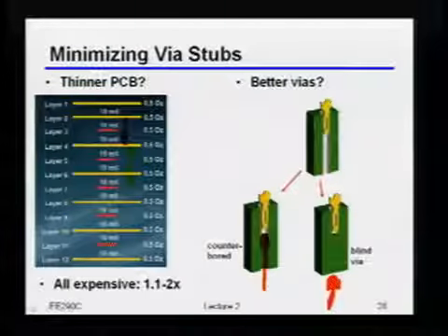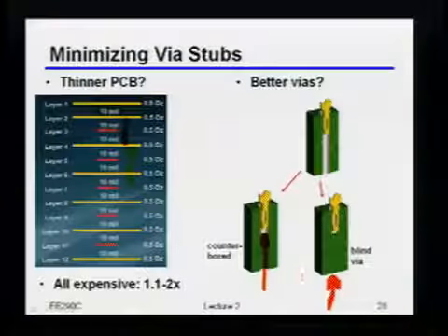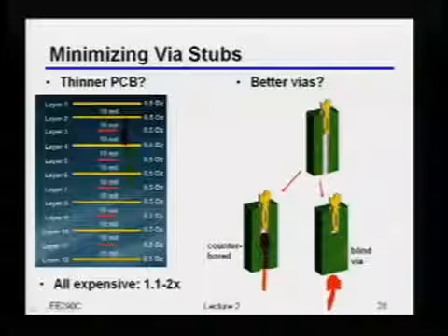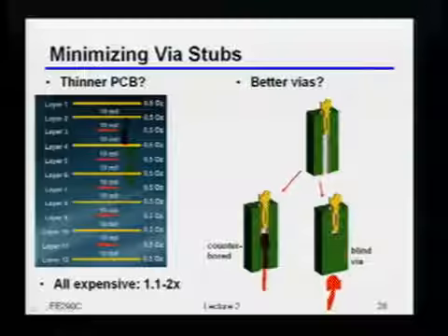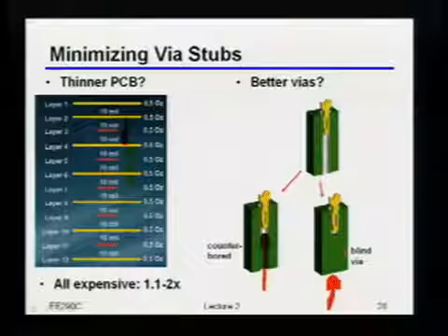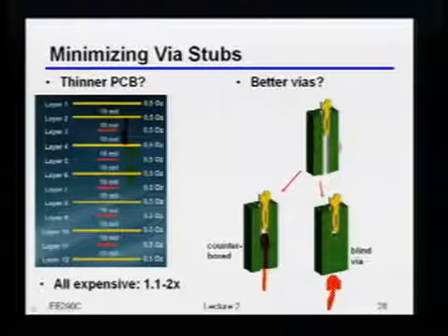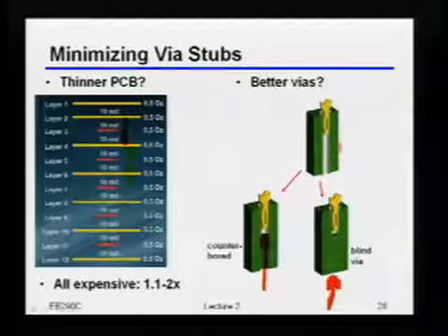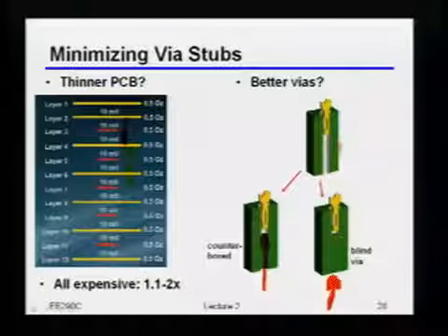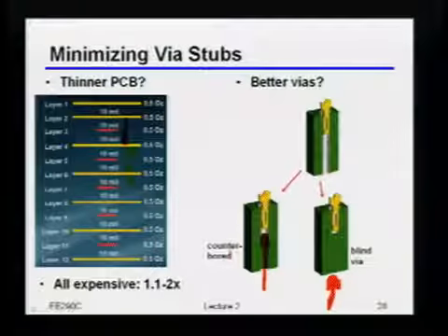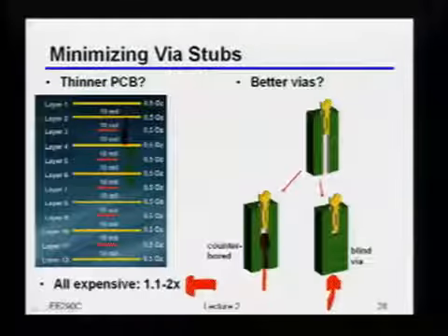So here, this is actually in the manufacturing process. Here, you really will fill in FR4 or resin or whatever you need to get that via to be filled. But now it is, as the name implies, essentially a blind via. To get that manufactured correctly is a lot more tricky than getting a normal standard via where you can just pour the copper in and then chop everything off on the other side when you're done. Okay? So bottom line is, there are maybe some things you can think of to do, but they're all pretty expensive. Okay? And usually no one wants to pay for it.